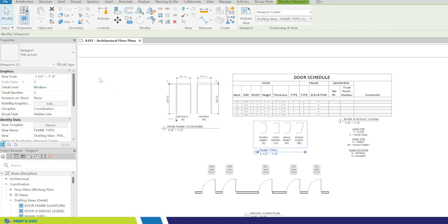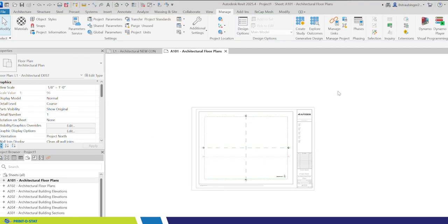Electrical equipment, mechanical equipment, plumbing fixtures. They don't always have everything in there that you want. Plumbing fixtures, you could put shared parameters in there for fixture units, per fixture. How many gallons per minute of flow? Well, everything you want to do. You could create that schedule to have all kinds of columns in it.